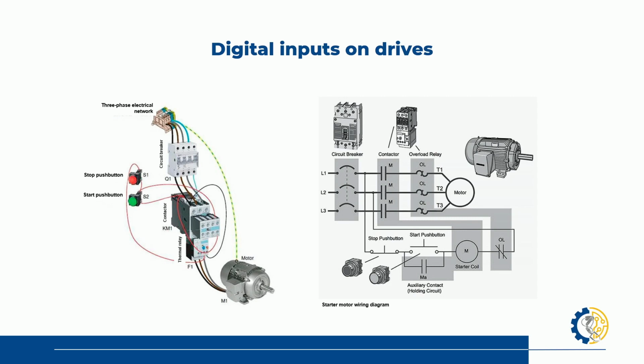Because sometimes salespeople want to give us our contactors or our coils that are 24 volts, yes, but in AC, 24 AC volts. So you need to be very careful with this, because I've had very bad experiences from being overly confident, and when we want to connect our contactor, it needs DC.